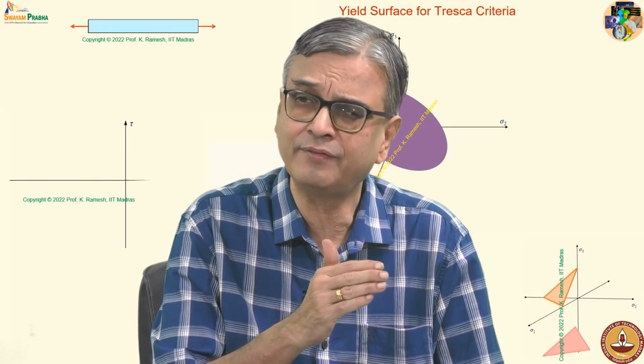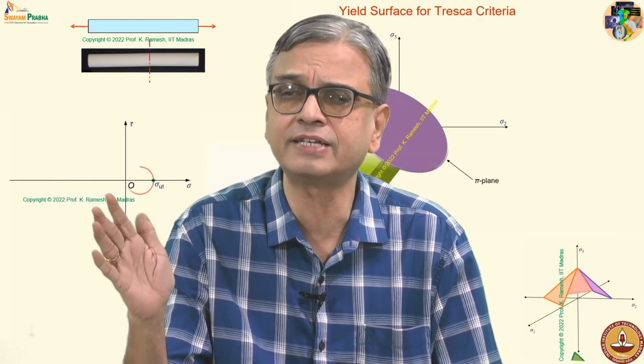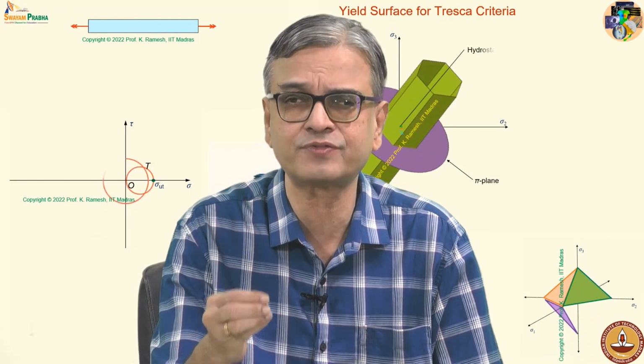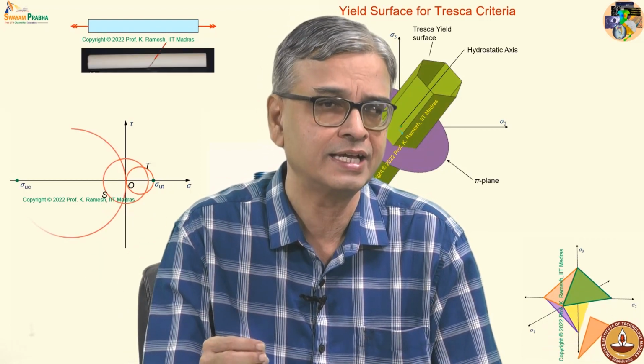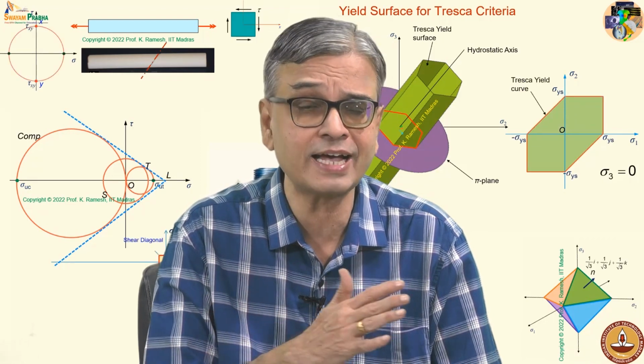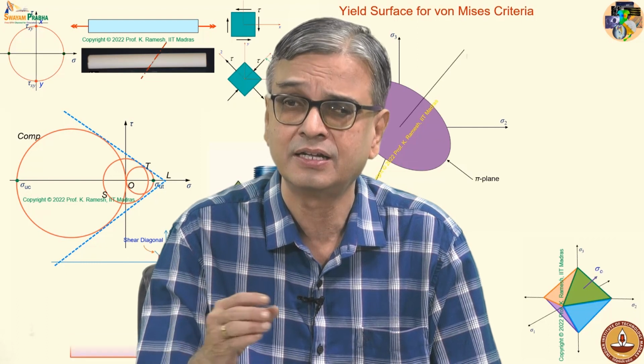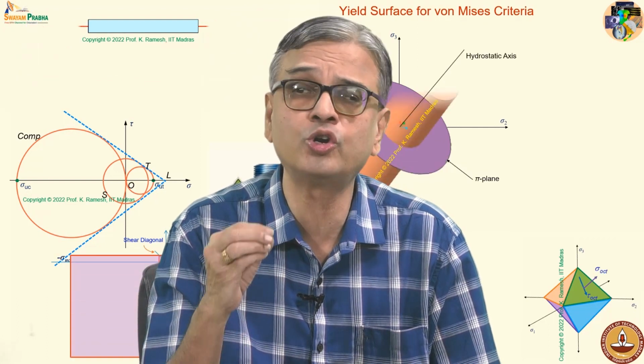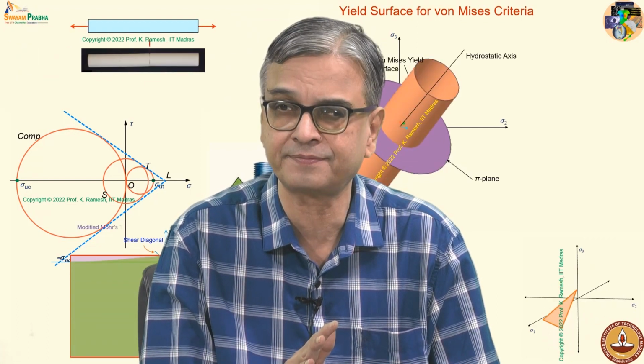Now, we never go anywhere close to yielding stress. You will have a factor of safety, you will have a design stress, and design stress is determined from factor of safety, which has multiple ways, multiple considerations go into how to decide the factor of safety.